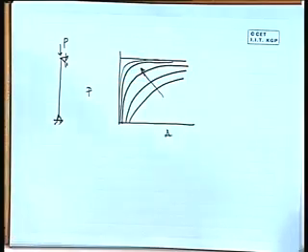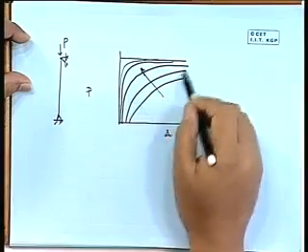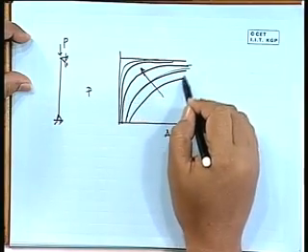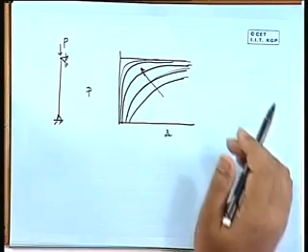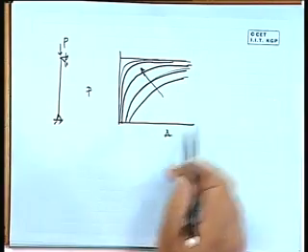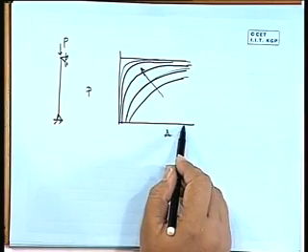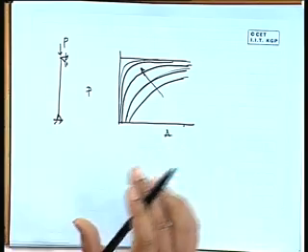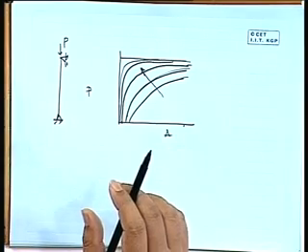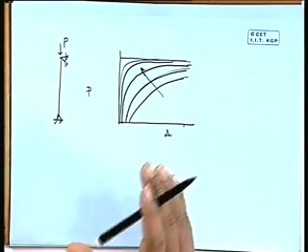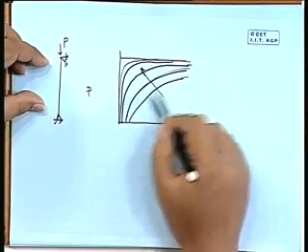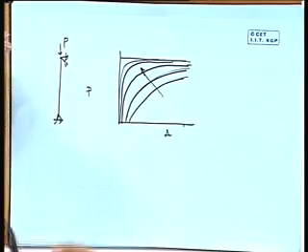We have the factor of safety to take care of that particular aspect. Otherwise, if we try to calculate this path, we have to go for a nonlinear analysis, because here deflection will be large, and we assume deformation is very small in any analysis. So that assumption is there. That type of study we can perform if we perform a nonlinear analysis. A nonlinear analysis is quite an advanced type of analysis.